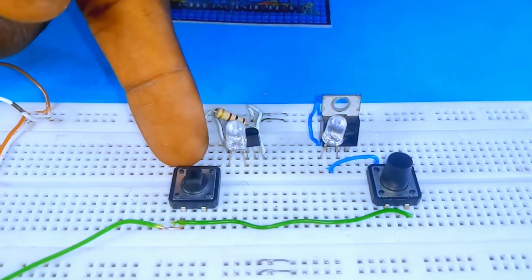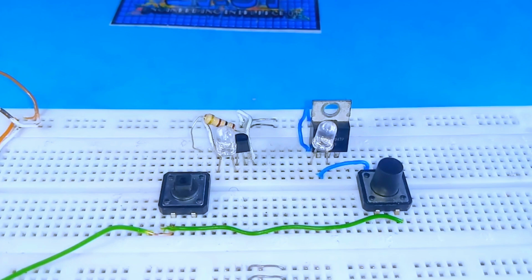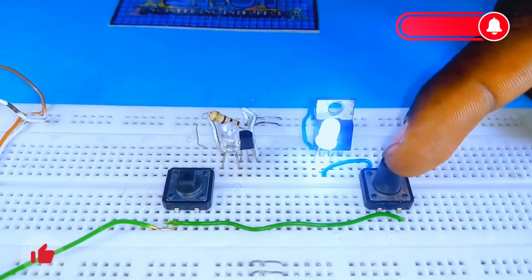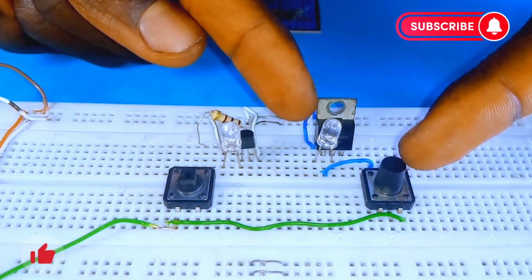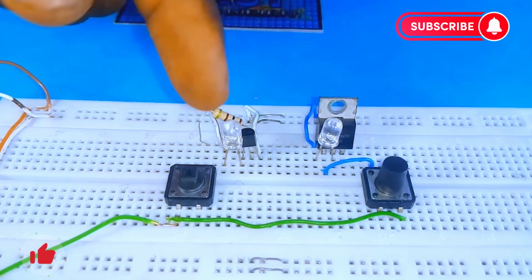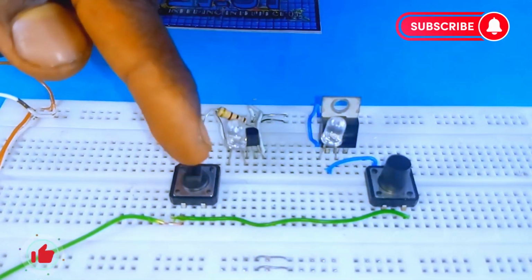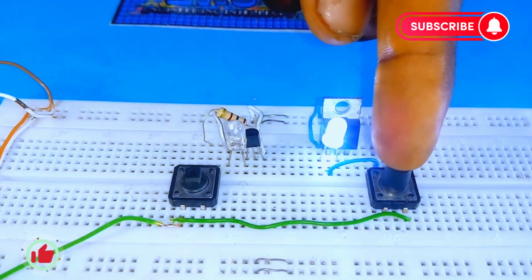The first switch will trigger the BJT and the second will trigger the MOSFET. And at this point, I have my 3 volt supply input. When the BJT switch is closed and released, we can see how fast it responds to switching. But for the MOSFET, when I first press the switch and release my finger, we can see a little delay before it goes off, like I added a physical capacitor to hold the charge. But for the BJT, it's nothing like that. So why is that? This is why MOSFET seems complicated to beginners, and with this, BJT is preferable to start with in learning electronics.